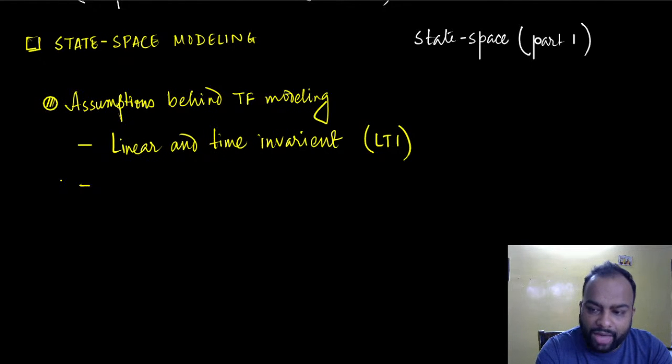But if you don't have a continuous time system and instead have a discrete time system, in that case you can have transfer functions, but the only difference would be the integral transform that you apply won't be the Laplace transform, but instead the Z transform. So you won't have a transfer function in terms of s, but in terms of z instead. So I'm not writing continuous time.